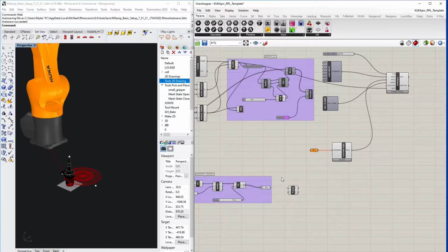So what we will do, we will type in our project component so we can actually project it. We are going to feed it our parametric geometry, and we also need to get an area point or a center point to actually orient it to the plane that we need, which is going to be our world XY plane. So from here, we'll type in area. We'll feed our geometry into the area component. This gives us an area of each of our geometries and a list of center points.